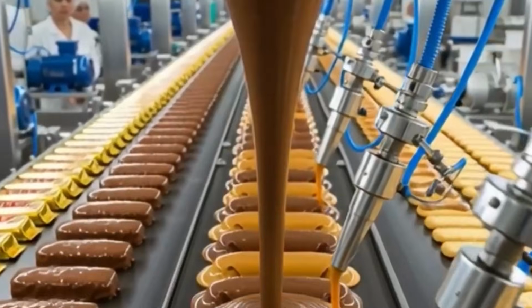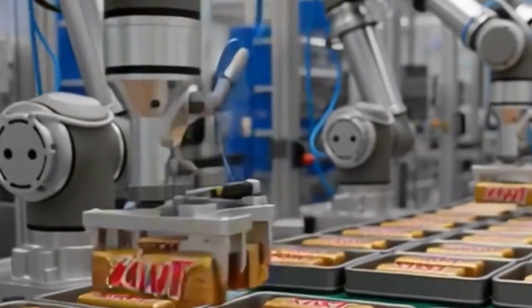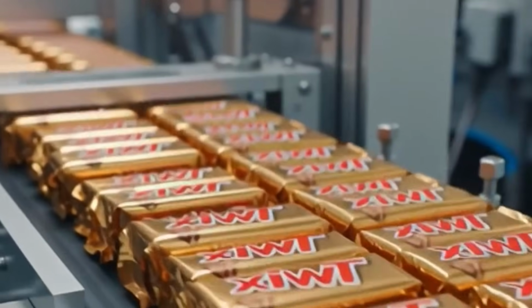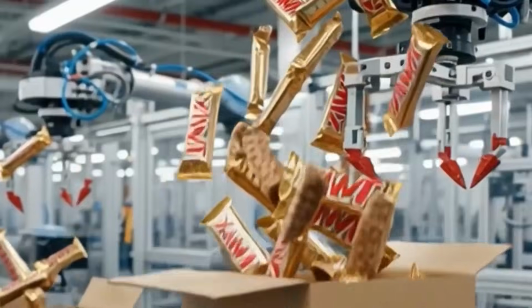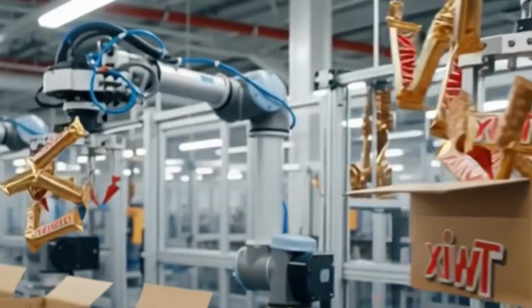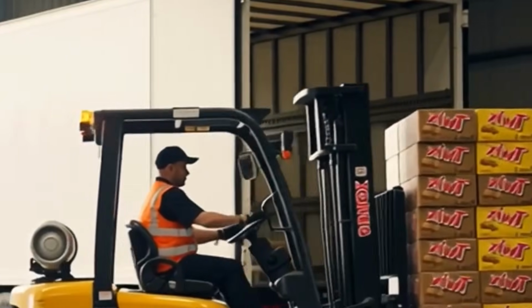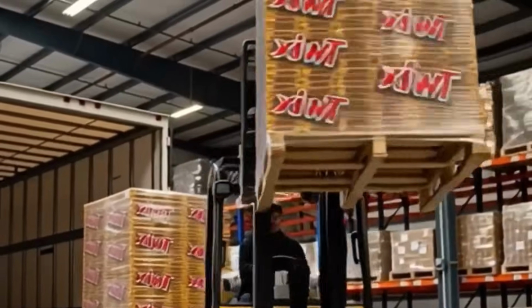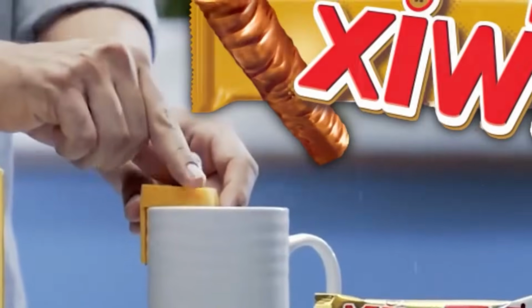Bars are individually flow-wrapped using printed multi-layer laminate films. The film is drawn over a forming collar and sealed using horizontal sealing jaws, operating at 135–145 degrees C. Before the end seal is applied, a nitrogen flush displaces oxygen within the wrapper to preserve product freshness and extend shelf life.